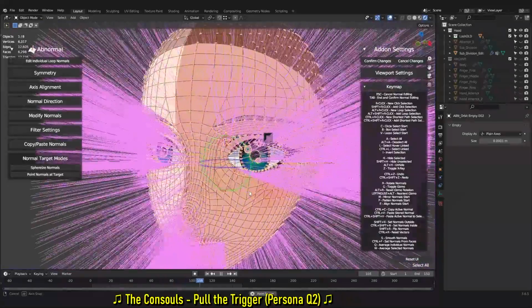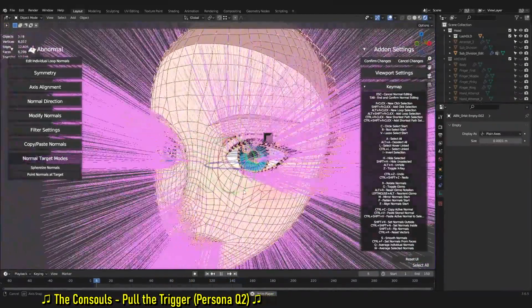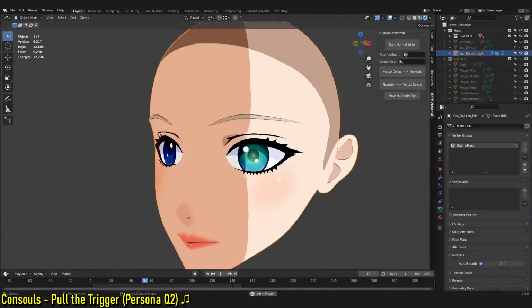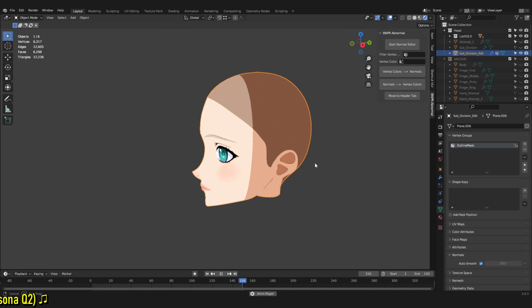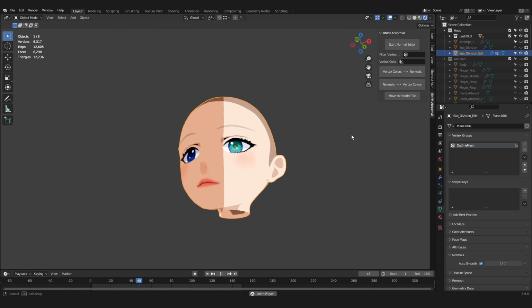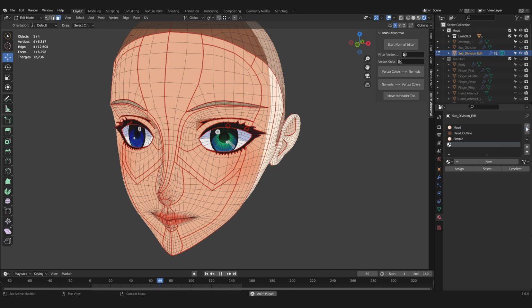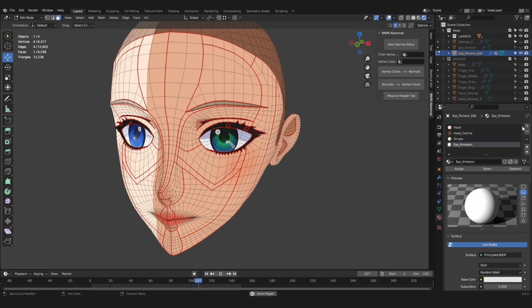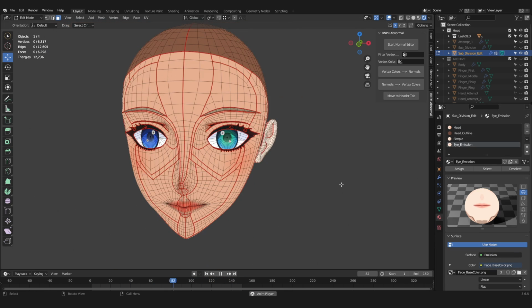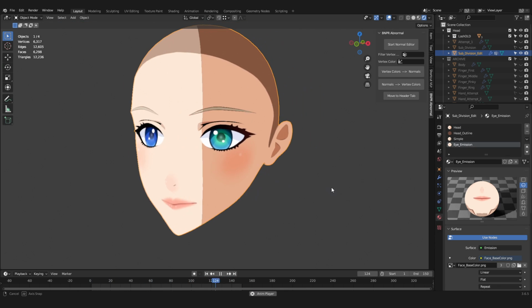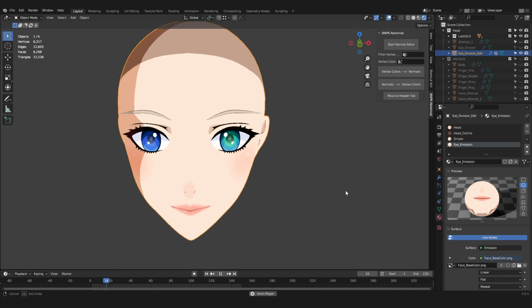You will have to make some adjustments when you eventually try to connect the head to the body, but I'll cover that in a future video. You can do the same for the eyes, but in my honest opinion, it doesn't look very good. So you have a couple of options. First is to set the eyes up with an emission material, similar to how we did the outline earlier, and assign a texture. This will result in the eyes never being in shadow. The alternative is to make the shading of the entire eye snap in and out.